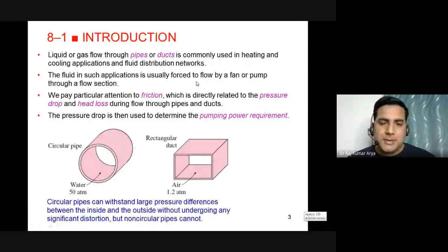Once the water is frozen and you are pumping from one end, excessive pressure would build up in the pipeline and it will burst. To avoid those failures, all pipelines are buried and sometimes provided a cover, to avoid outside heating or cooling effects.